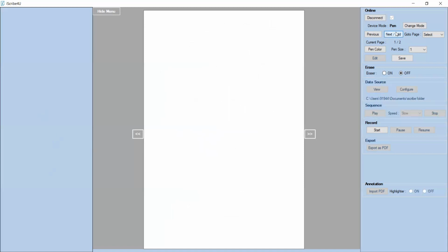I'll go to the next sheet. So let us derive an equation for TP now. To find an expression for TP, what we do, how do we find the maximum and minimum of a function? We differentiate that function with respect to time and we will be equating to 0. So that's what we will be doing here to find the expression for peak time TP.